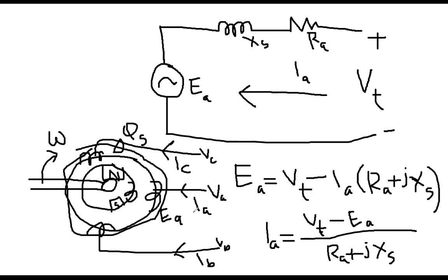So what is that rule? That is called Lenz law. Can you remember Lenz law from physics? L-E-N-Z, Lenz law. According to Lenz law, it will oppose the main voltage. That is its characteristic. EA got generated because of the application of voltage, but once it is generated, it starts opposing the main voltage, which is called Lenz law. So that is the meaning here.